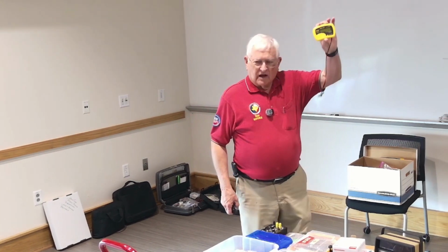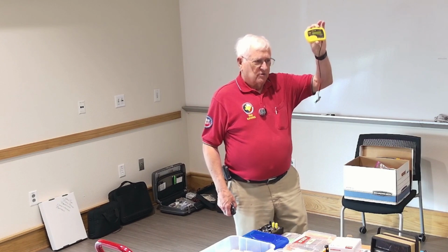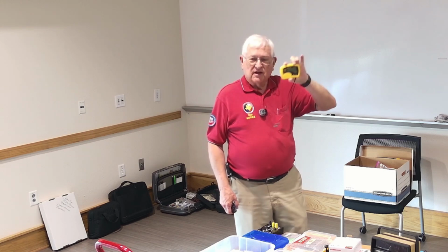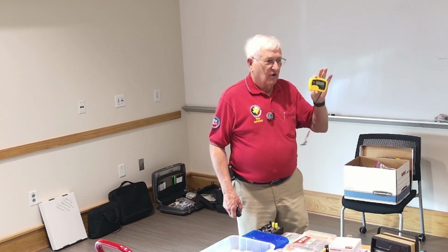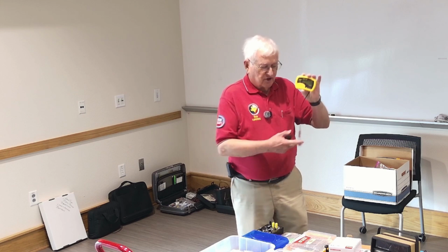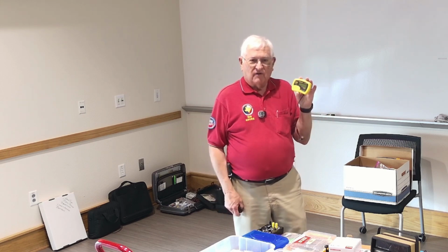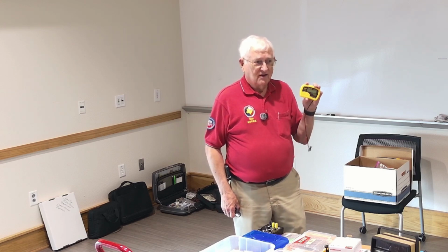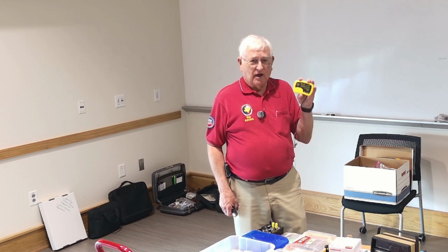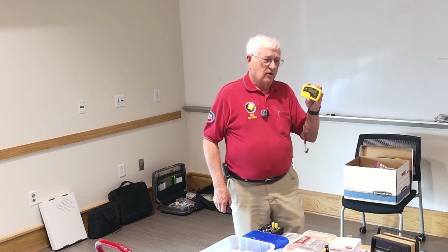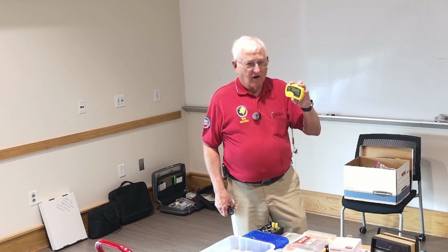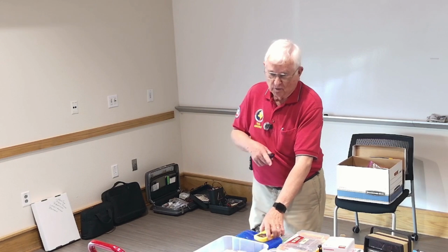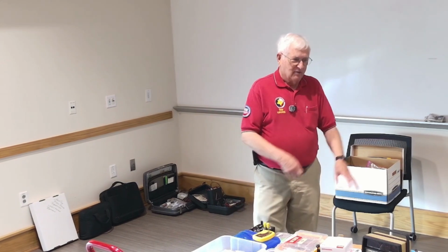This little guy right now is $119 on Amazon. Unfortunately, I only have one. I wish I had one for everybody, but I don't. But this thing is absolutely marvelous. How they do this, I don't know, and I don't really care. You basically just hook it across the component, press the start button, wait 5 seconds, and it says, this is an inductor, it has 4.7 microhenries of inductance. This is a resistor, it's 1.2K. This is a capacitor, it has 0.1 nanofarad or whatever. It just works, and it's great, very accurate, very consistent, and very repeatable. So I use that as my standard when I'm evaluating the other instruments.